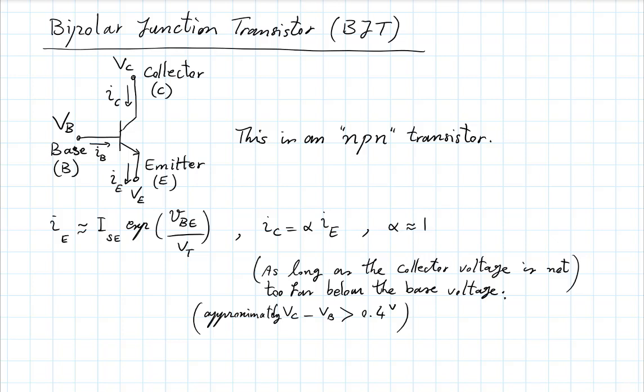And the current of a diode can rise with the applied voltage to the diode very, very steeply because it's an exponential function. So what this device is doing is taking a voltage input between the base and emitter, giving a current at the emitter, but then essentially duplicated at the collector, which is an exponential function of that voltage difference. So it's giving you a current at the output that's an exponential function of the voltage at the input.